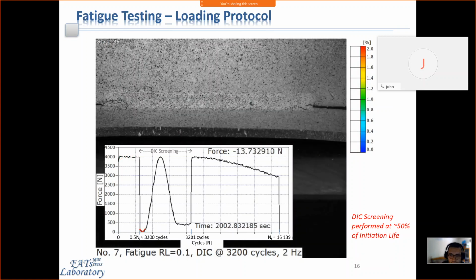In this case, did the crack initiate on the weld or the base material? This one is the weld, right at the edge of the weld here. So on this thickness combination, all your cracks were on the weld? Excellent question. It depends on the load amplitude. If you have a high load amplitude, or a high shear stress or high stress at the root or the notch of the weld, you are going to have this initiation in the weld, and it's going to generally propagate throughout the entire longitudinal axis of the weld.